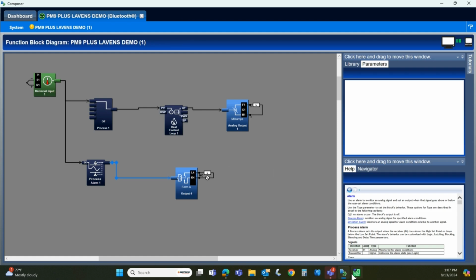One of the differences I was alluding to is on the Watlow side, I can look at a saved image, but I cannot make any changes. So you would need to have the instrument on hand to be able to make and save configuration changes.